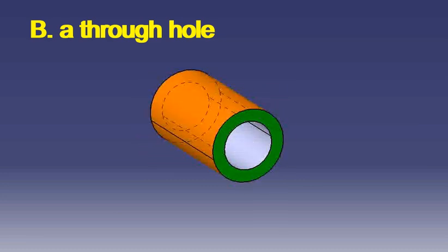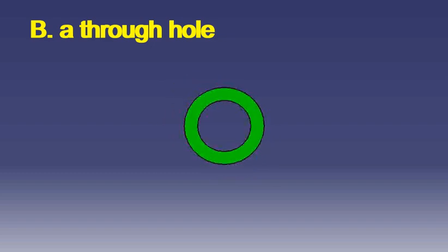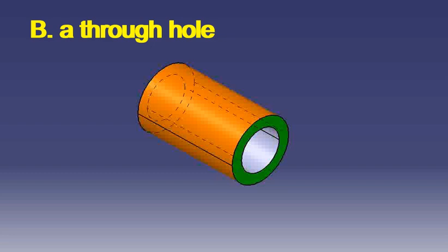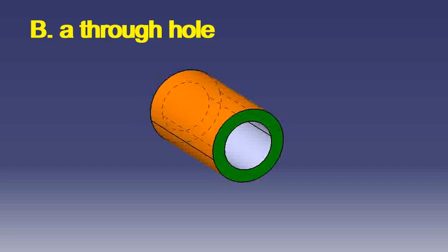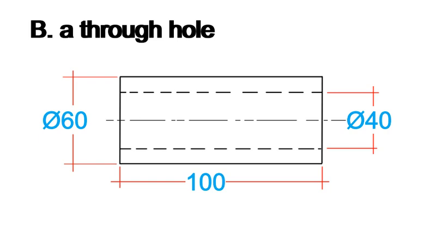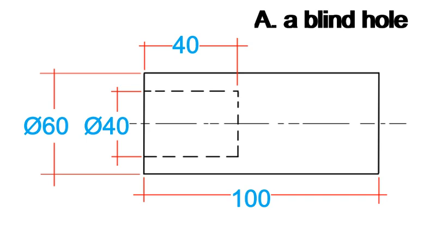The key is that the combination of the diameter symbol on the hole and the center line on the main view instantly tells anyone reading the drawing that this is a round, coaxial feature. They don't need to see a side view to understand the circular nature of the part or the hole. This one view, with its smart use of symbols and notes, conveys all the necessary information without any clutter.